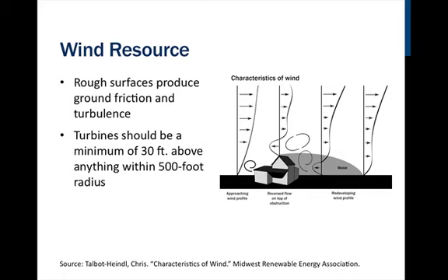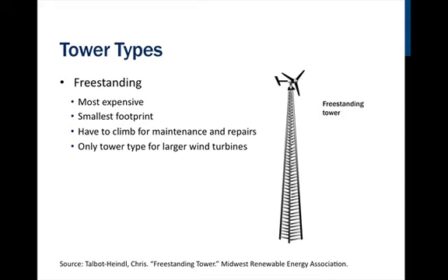If you're in an area with dense vegetation or buildings, a new effective ground level is established at approximately the height where the branches of adjacent trees touch. Below this level, there is little wind that you can use, and it will have high turbulence, making most of the wind unusable for energy production. In order to lift the wind turbine high in the sky, we're going to need some sort of tower.